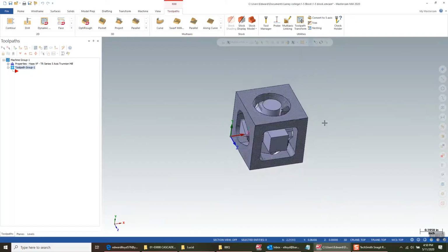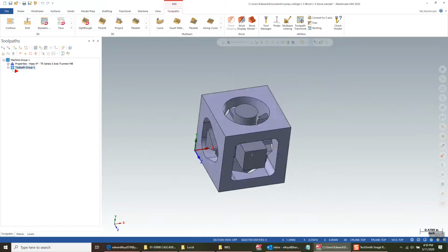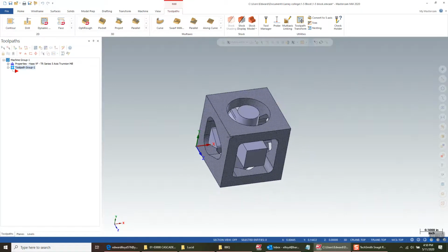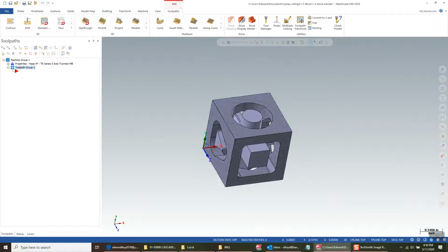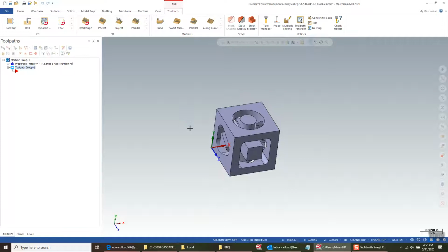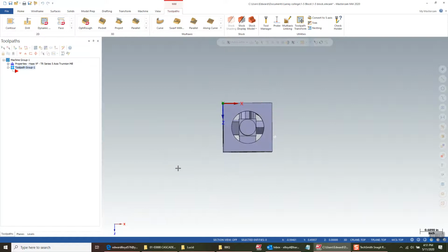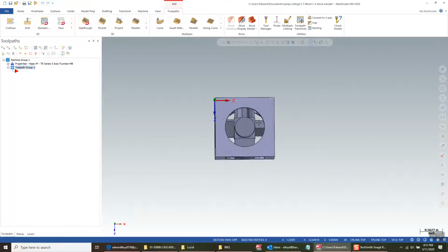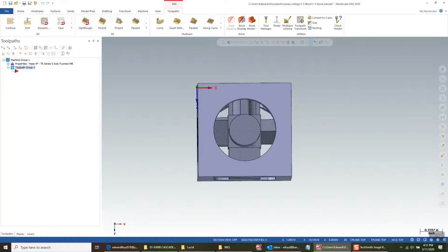Okay, so we're just gonna do this as fifth axis basic setup. So first thing we need is something that's going to be our top plane. So when we're looking down through the spindle, what's going to be facing up when everything is at 0 rotation. So the way we've done it so far is we've had this circular one first because that's where we put the engraving for Laney College.